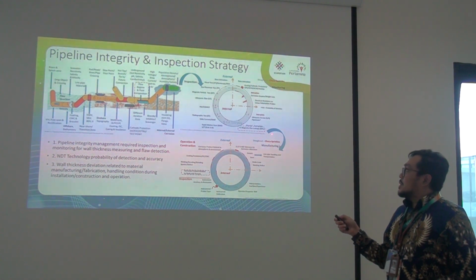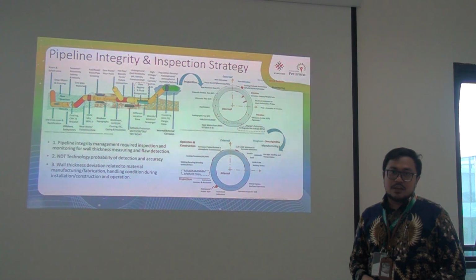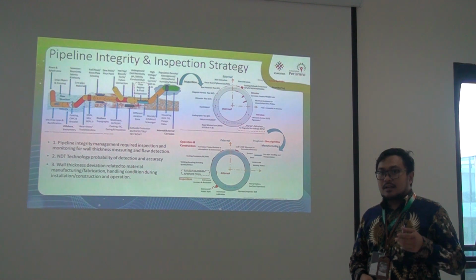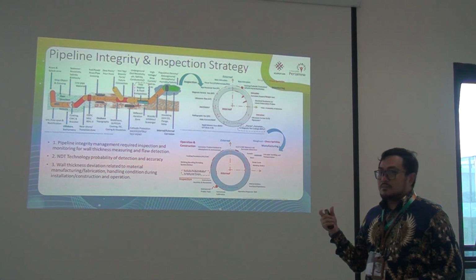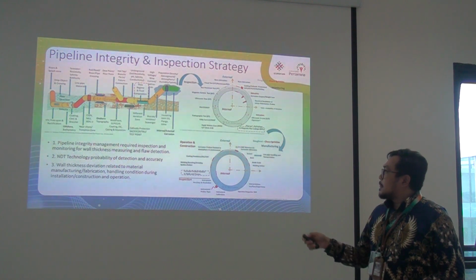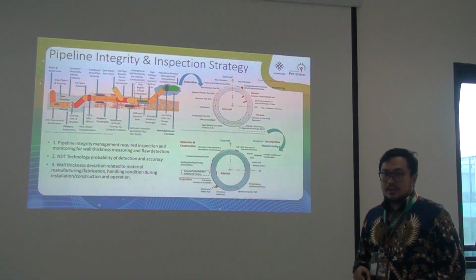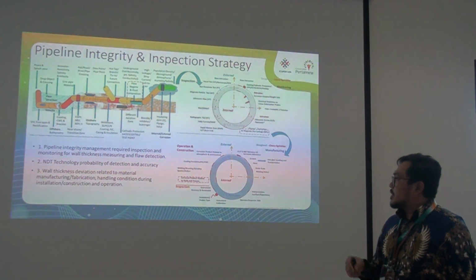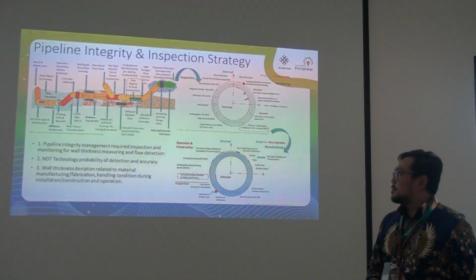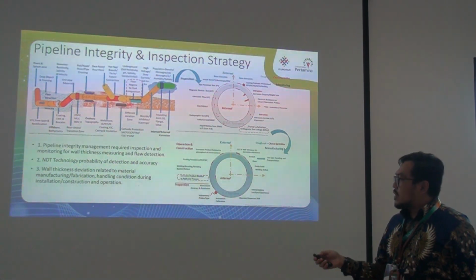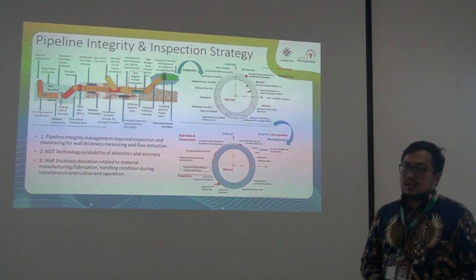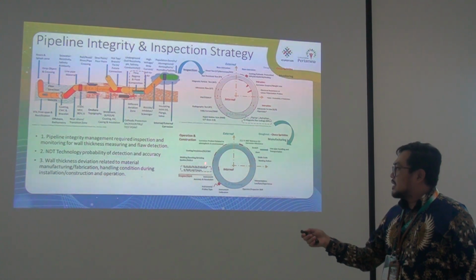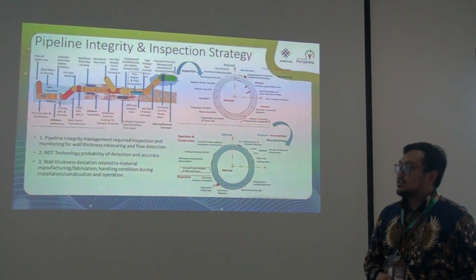Let's say we just mention the ILI-MFL magnetic flux leakage inspection, which has the capability to detect inline defects and also internal and external defect conditions. This is for the manufacturing specific differences about the wall thickness. We know in manufacturing we have the 12.5% tolerance for any line pipe mechanical processing, and also the thermomechanically controlled processing. We have differences in the wall thickness condition.